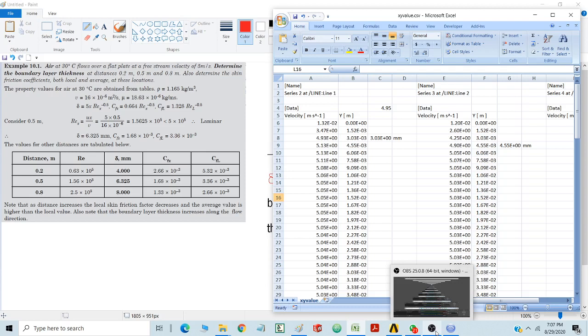There is no such way to find the value of boundary layer thickness directly in the software. You have to analyze the points by exporting them into an Excel file, and then you have to see that. I think it will definitely help you to understand how a boundary layer is developing over a surface.